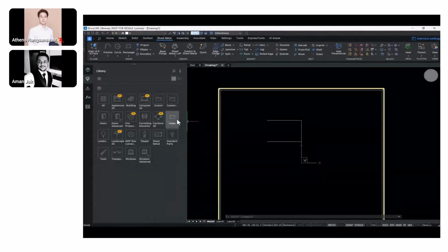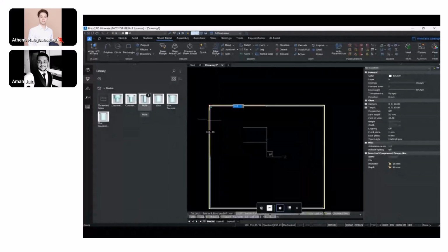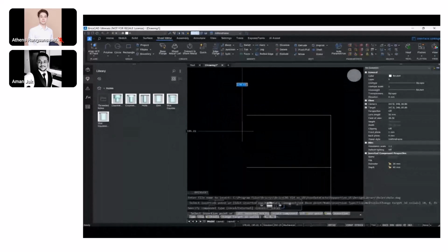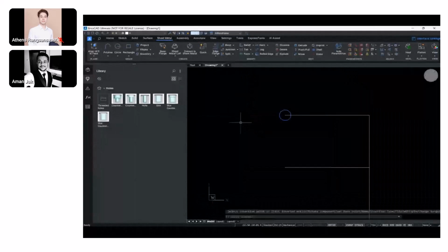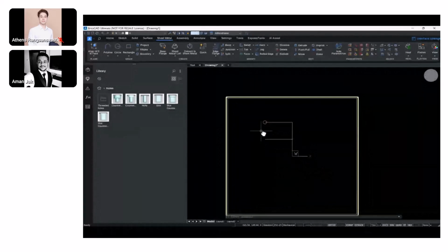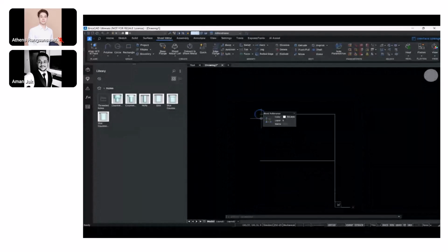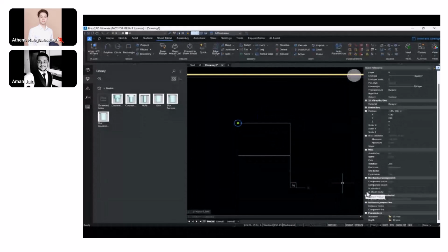There's a 3D library and a 2D library as well that comes along with the installation. And here I'm taking a hole. This is actually a 3D parametric hole that's available within the library. I'm just placing it, snapping it on the top of lines that I've just created. And very simply, I can then mirror these lines, and change the diameter as per the diameter of the switches that I'm going to insert.